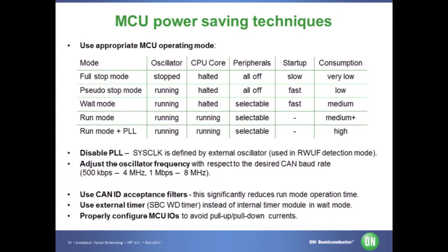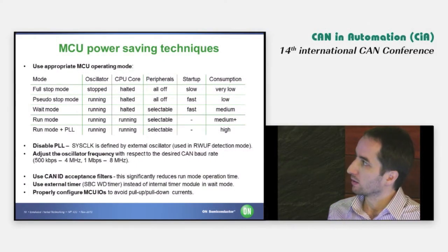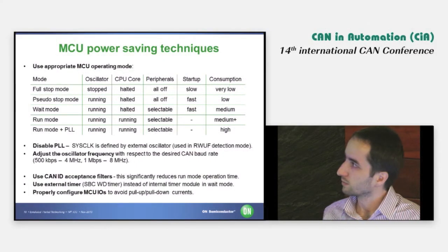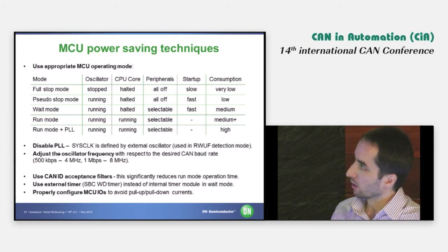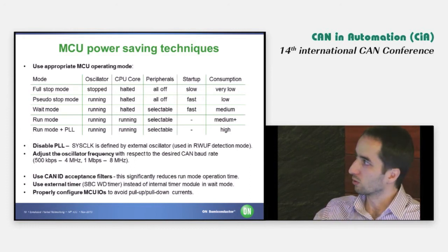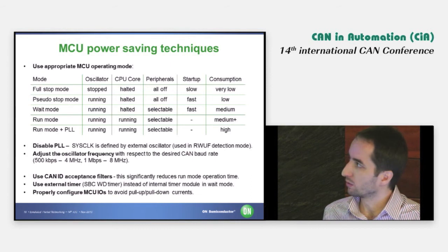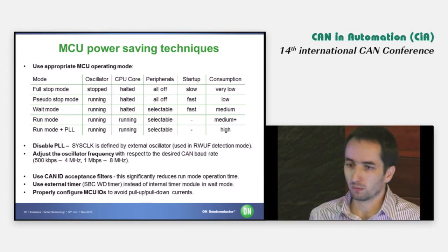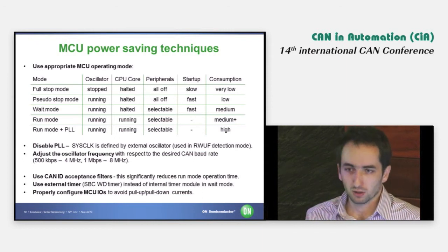The microcontroller provides several low power modes, and the most important for us was the pseudo stop mode, where the oscillator is running, so it allows a very fast startup, but the clock is not distributed to the core of the microcontroller, nor to the peripherals. It means there is a low current consumption.